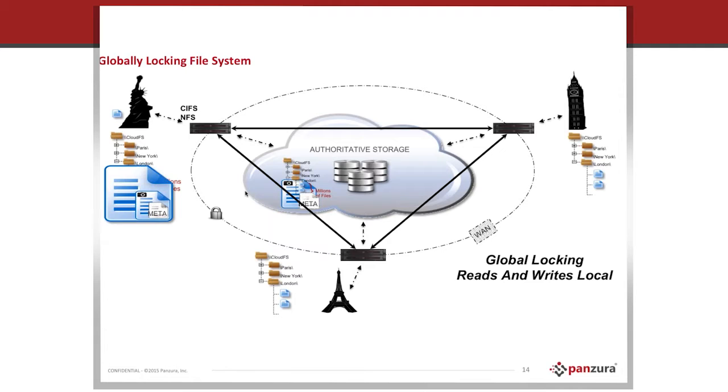Now, if we were to say, okay, every 60 seconds we're going to take a snapshot of the changes in the model and push that up to the cloud, and then every 60 seconds the other devices were to pull that data down, that would be roughly 2 minutes before the changes in the backup folder were replicated across multiple sites. And that's just way too long for Revit to be able to work efficiently, and for you to be able to work inside of Revit with multiple people in the same model in 2 different locations.